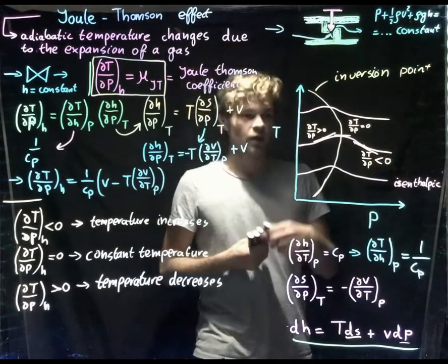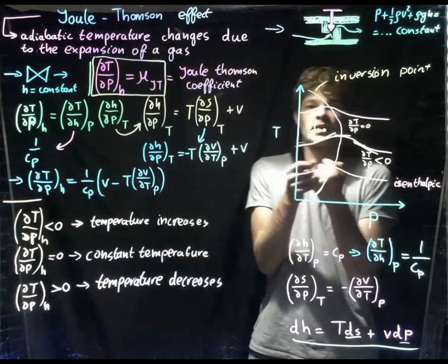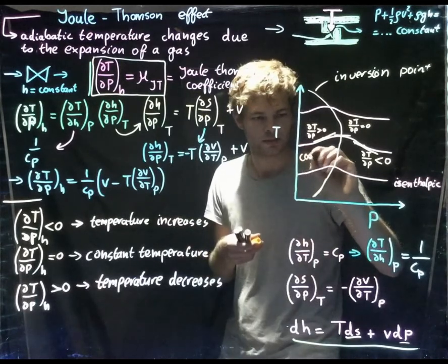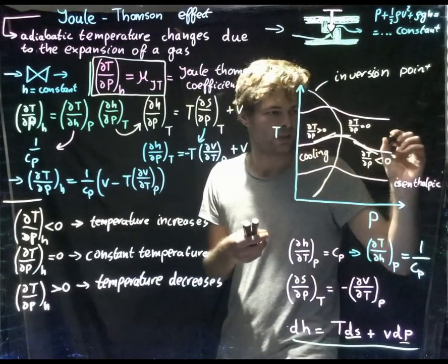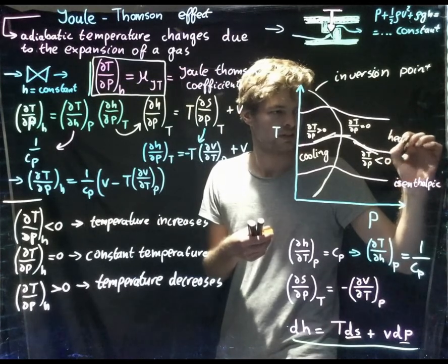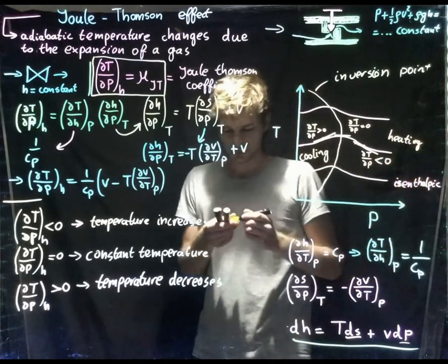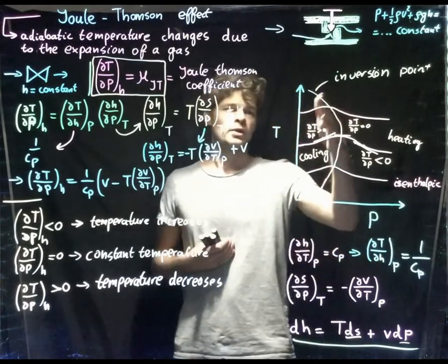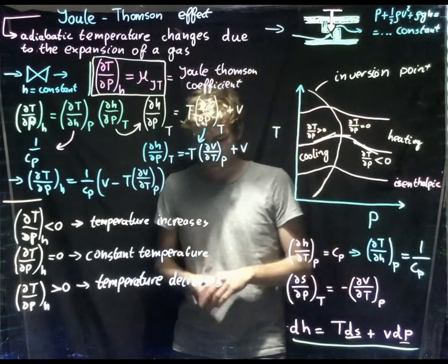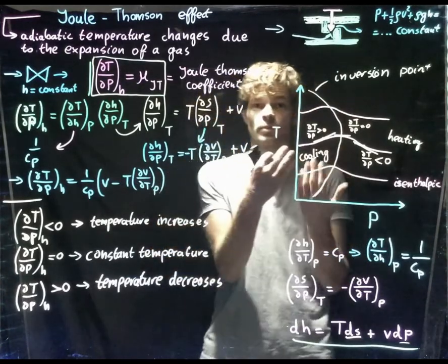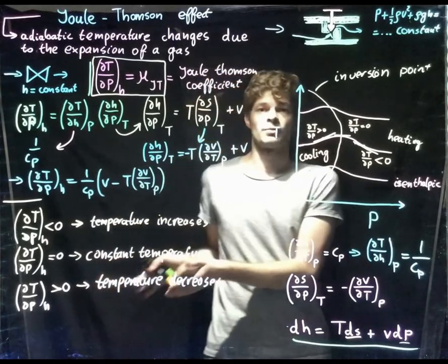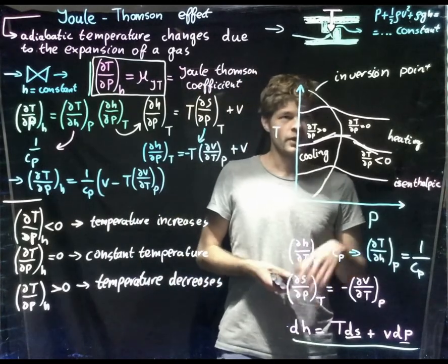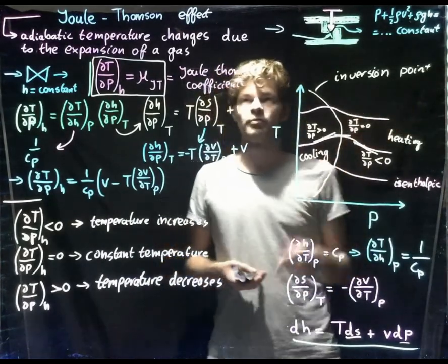So over there, the behavior of the gas will change from a gas that is cooling to a gas that is heating up. So this inversion point determines when it will happen. It's actually a material property, so air has another inversion point compared to helium or to nitrogen. So it's a property of matter.